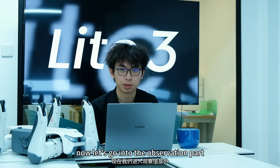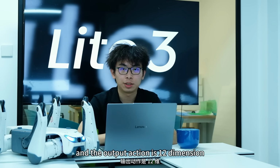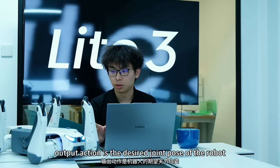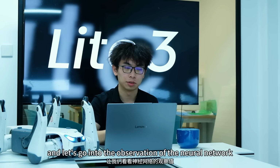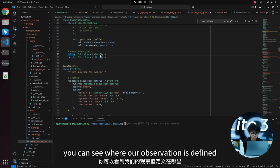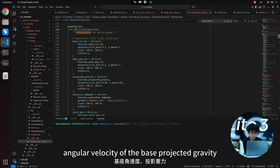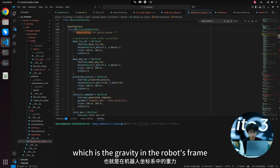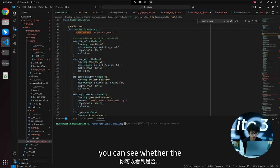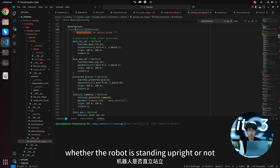Now let's go into the observation part. Our observation for the neural network is 45 dimensions, and the output action is 12 dimensions. The output action is the desired joint pose of the robot. Let's go into the observation of the neural network. If you click here, you can see where our observation is defined. In here we have the linear velocity of the base, angular velocity of the base, projected gravity, which is the gravity in the robot's frame. You can tell from the projected gravity whether the robot is standing upright or not.